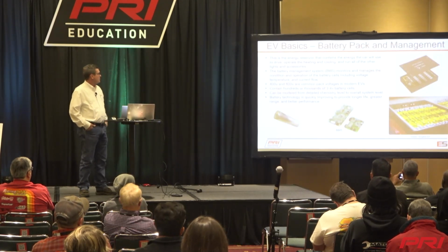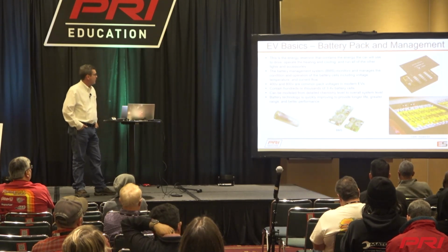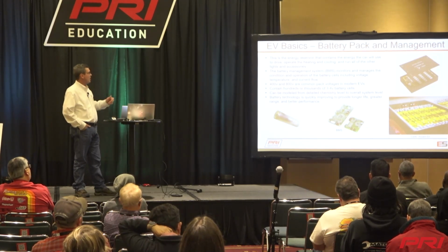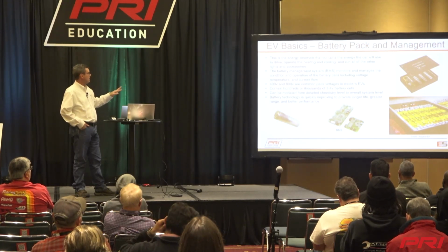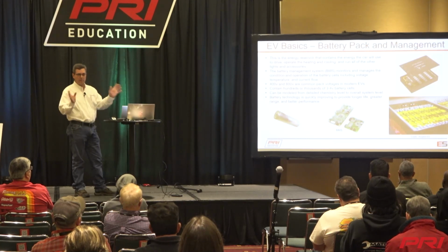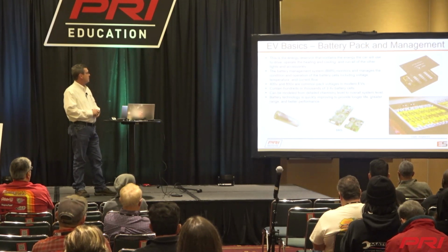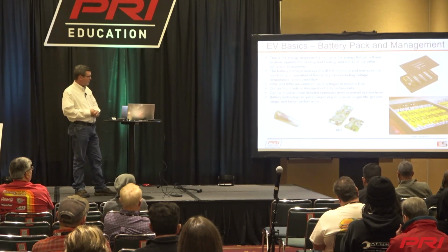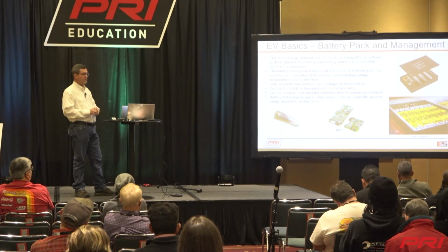Some of the components, the EV basics. The first thing is the battery pack. This is the energy reservoir that contains all the energy that the car will use to drive. It operates the heating and cooling and runs all your other ancillary accessories. The battery management system, the BMS, is a computer all on its own. It monitors and manages the condition and the operation of the battery cells during operation. It's very important to control the temperature and the current flow.